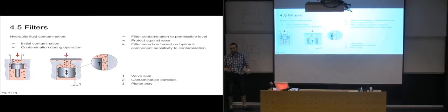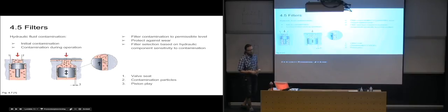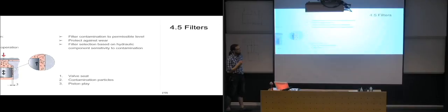While a huge piston, as you have in the heave compensation systems that they use on cranes on boats, which they use to compensate for the heave motion of the waves, they are like quickly a meter in diameter, these huge cylinders and pistons. There you often have quite a lot of piston play, so that you have room for larger particles. It's usually filtered well below what it can handle, though. But it's a component that can handle very large amounts of contamination.